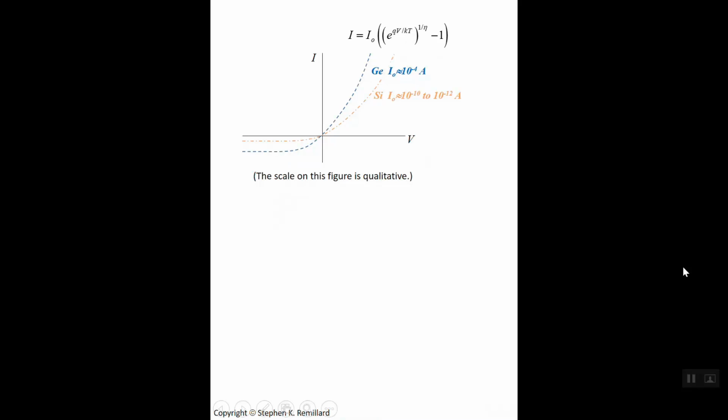So two salient points to remember about PN junction devices. One, there is a built-in potential, phi sub bi. It's a consequence of the doping level, and it's going to keep coming back to us, so we'll have to get comfortable with the idea that when you connect a P and an N-type semiconductor together, there's a potential hill that carriers need to climb to cross over to the other side. The second salient point is that the band gap is a constant throughout a junction fabricated from the same piece of semiconductor, and it does not vary with either doping or with bias voltage.